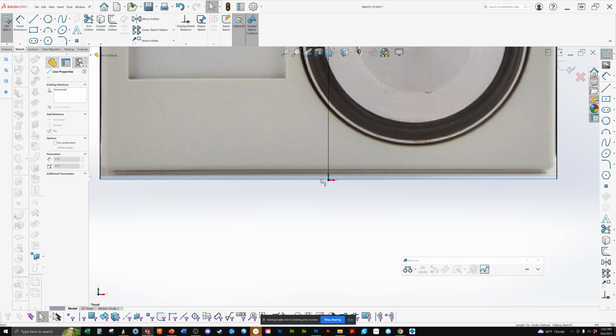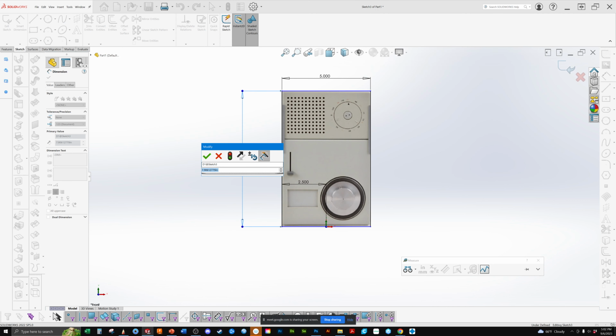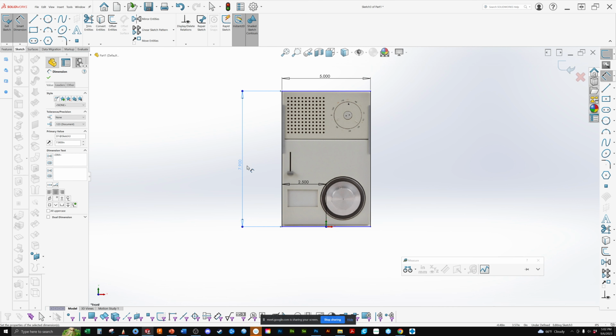So now, if that's the height they have it at, I'm matching their sketch, I'm going to say, well, we'll make it 7.9. Because 7.906 is just an annoyance, and no one's going to recognize the 0.06. So there we can extrude it.